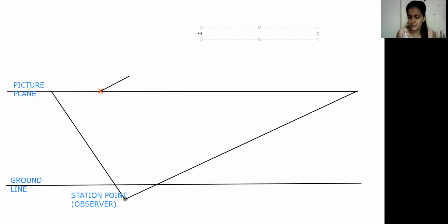And how many is the number of steps? There are only 3 steps. A single tread is 0.3 meter, but we have considered it as 1 centimeter. So we are going to take 3 steps, and each is 1 centimeter. So multiply it: for 3 steps, we need to draw a 3 centimeter line. At 30 degree angle, we are going to draw the line of 3 centimeter and divide it into 3 equal parts so that we can draw the steps.